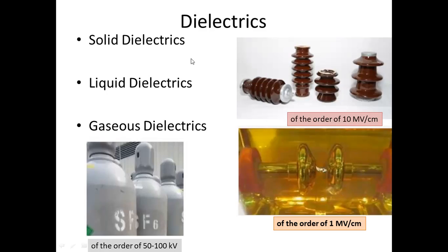As we have observed, transmission lines are separated from each other, so by separating them we have actually installed a gaseous dielectric between these two transmission lines. In power system terminology, we call it clearance: the clearance between the transmission lines and the clearance from the earth.